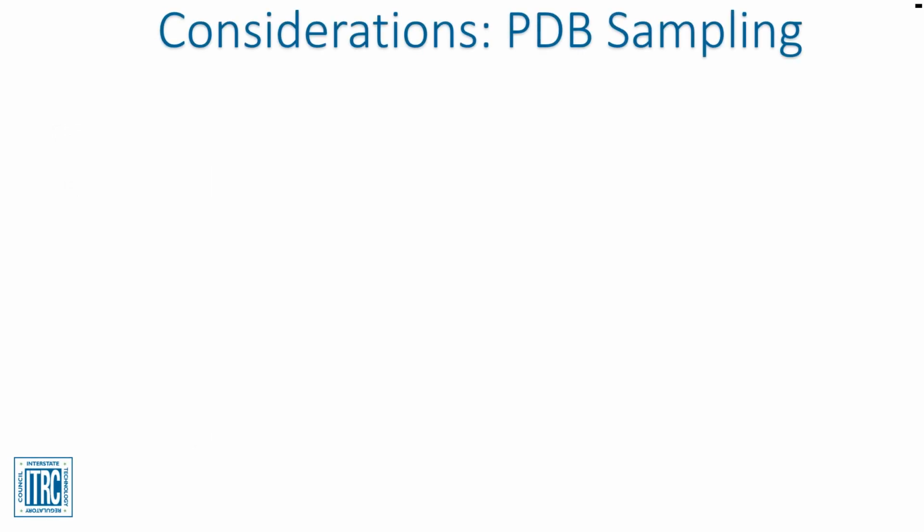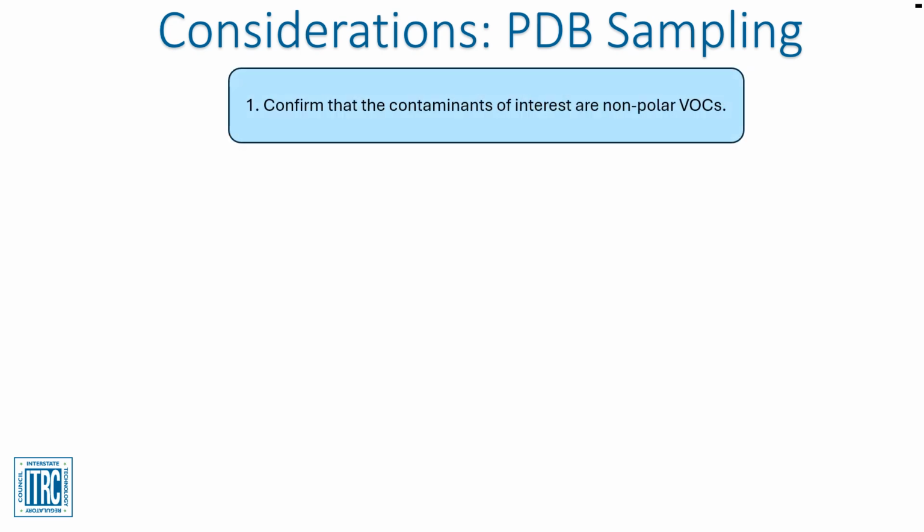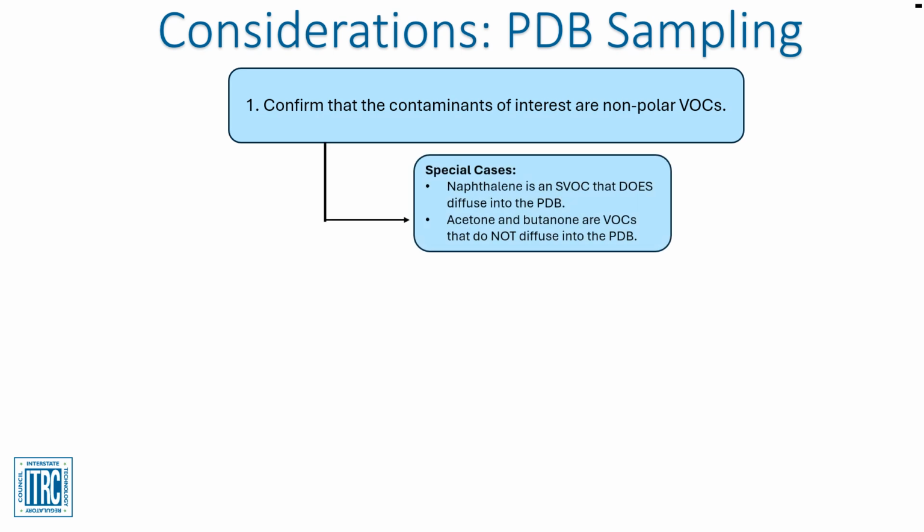Before using PDBs on a new project, consider the following. Confirm that the contaminants of interest are nonpolar VOCs. Note that there are special cases that do and do not diffuse into standard PDBs.